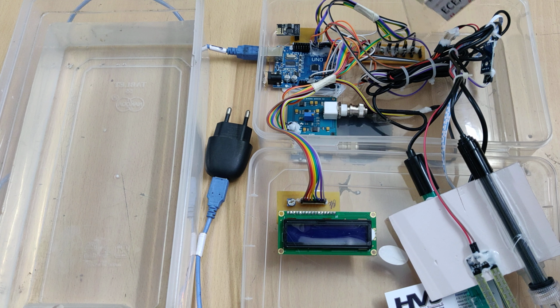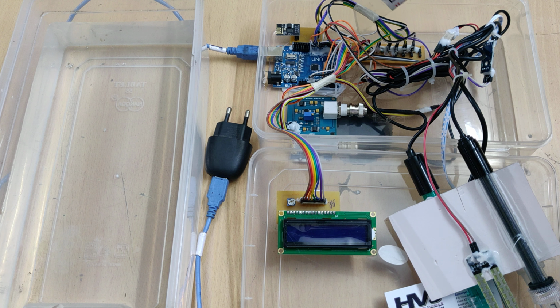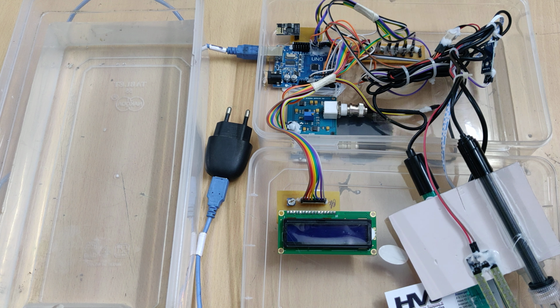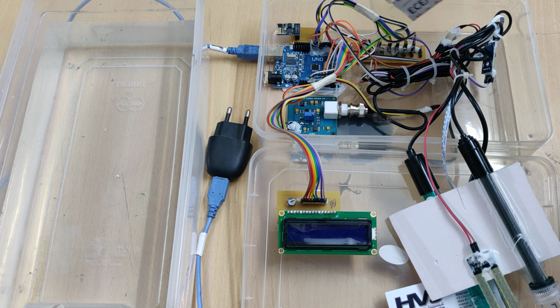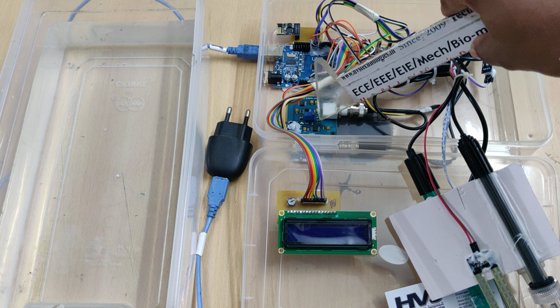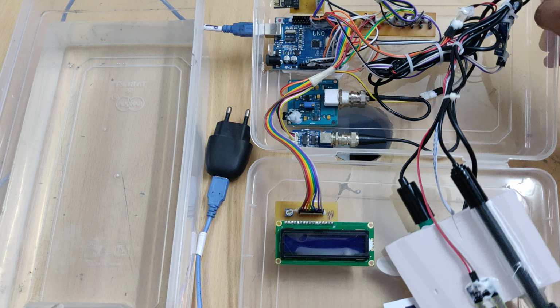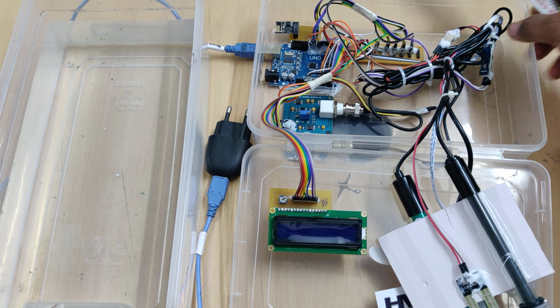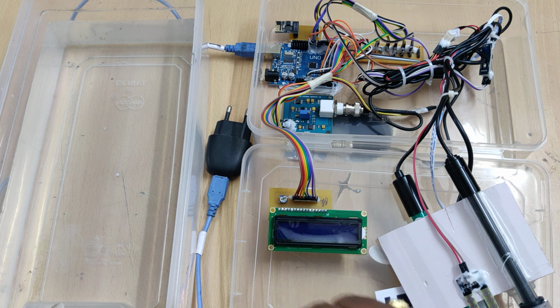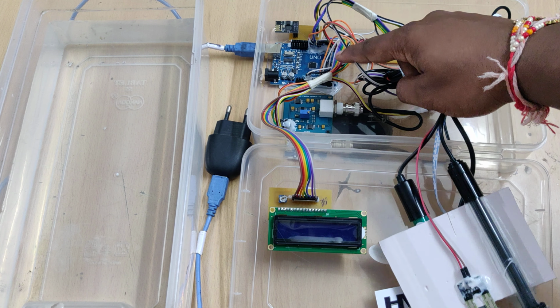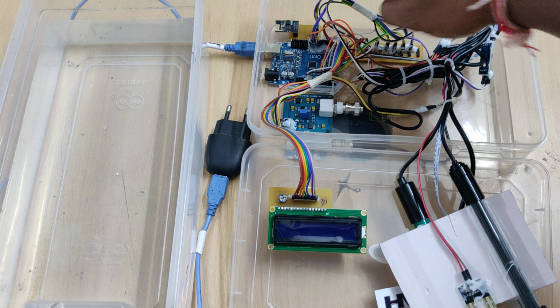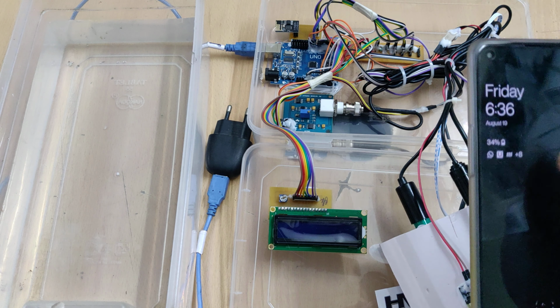So this one is the breadboard. In order to distribute the 5 volts power supply throughout these input and output modules, we are making use of this breadboard. And next, these two are the driver boards for pH and DO. The LCD is interfaced at pin number 2 to pin number 7, and the Wi-Fi module at pin number 8 and 9. So before switching on the kit,